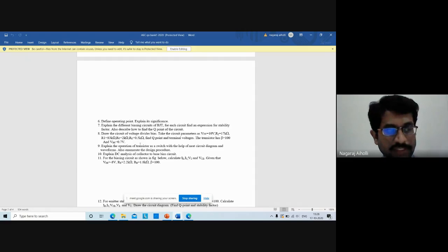And VC is VCC minus ICRC. I have already described this when taking the class, and I have also provided the notes on that. Just go through that. VC is given by VCC minus ICRC. So these are the equations for the terminal voltages, that is VE, VB, and VC.